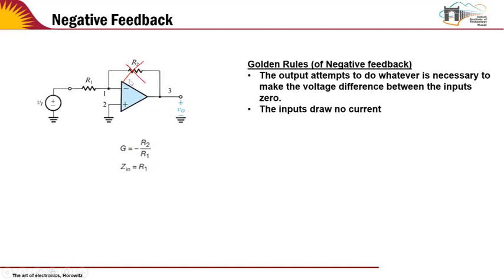Now when I have a feedback path over here, now that I have this R2 connected, let's take some example. Let's say the input were 5 volts. Supposing I'm applying 5 volts, then V2 minus V1 is minus 5 volts. Let's assume initially the system is just starting. Actually, it cannot be minus 5 volts because it depends on the value of V out. So let's assume initially V out is also 0. So that makes it easy. So V out is grounded.